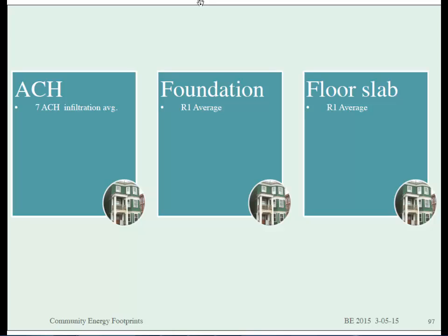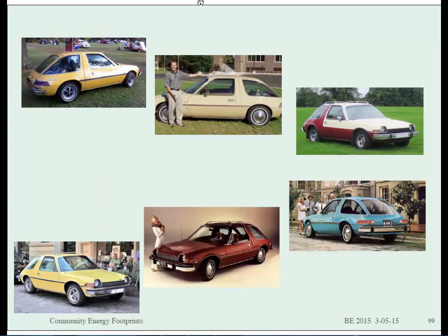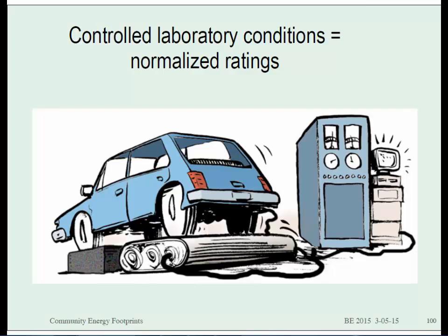And these are what eventually, through public record and enough field research, actually build the inputs that are necessary for the modeling. So back to the automobile parallel for just a moment. It's a beautiful automobile. If we were to be talking cars instead of homes, how would you back into an energy rating for a car if you couldn't find the data online anymore? Well, you would take a sample group, gather data from each of the typologies in question, and sure, there may be minor variations in options and components, maybe a few model years range of difference, but we're going to get a pretty good sense of where that model is performing. And as with HERS, we would conduct testing under similar control conditions so that we arrive at normalized data.